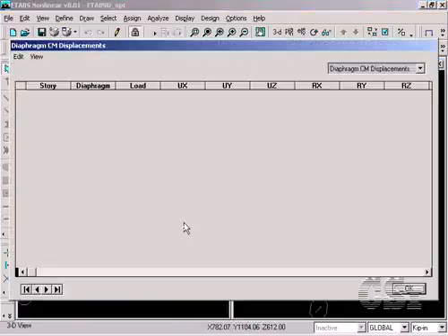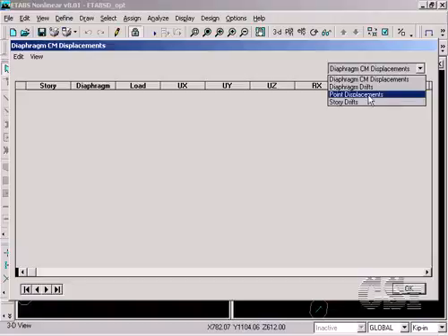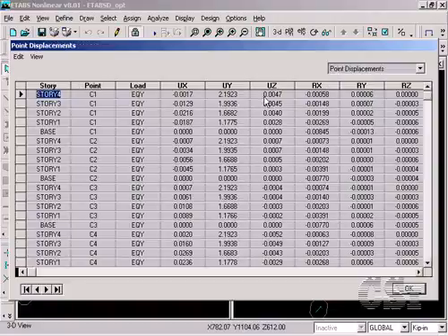On the next form, select Point Displacements, and note that the maximum lateral displacement is typically 2.19 inches. We will assume that we have a target displacement of 1.5 inches for this building, so we will need to perform a redesign and resize the members to reduce the deflections.